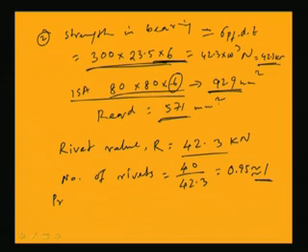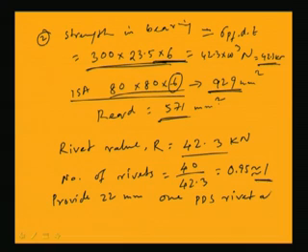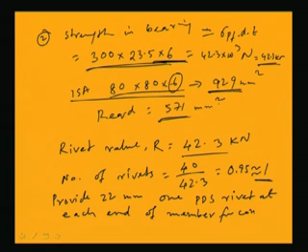So, we can say provide one 22 mm power driven shop rivet at each end of the member for connection. Okay. So, we will provide one 22 mm power driven shop rivet at each end of the member for connections, right.